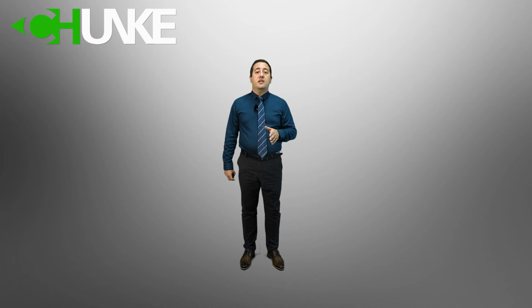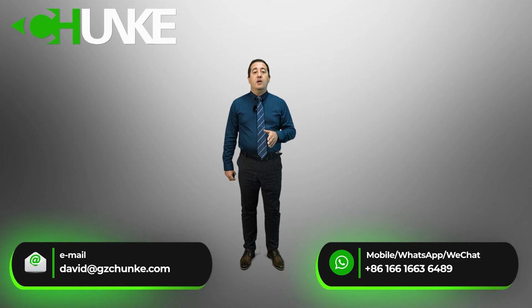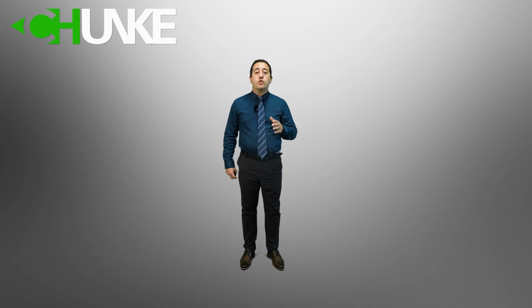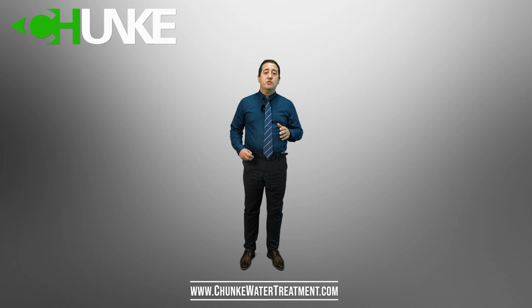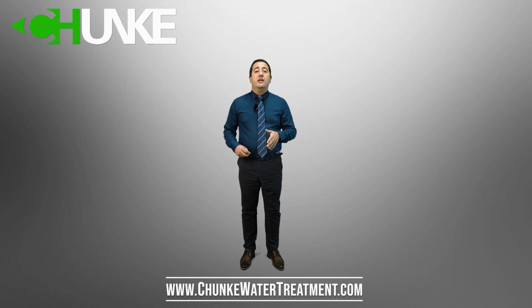For large systems, 6 element vessels are standard, but vessels with up to 8 elements are available. For smaller or compact systems, shorter vessels may be selected. For a small system like 250, 500 liter per hour, just one 4040 or 2 pieces of 4040 elements can be enough.